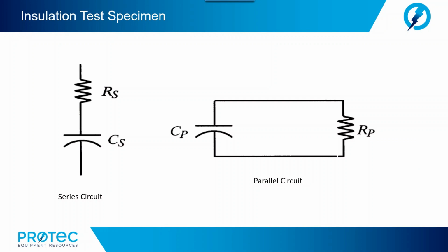Insulation systems associated with many types of high-voltage power apparatus and devices often consist of a mix of non-homogeneous component parts. As such, a complete and highly accurate schematic representation of an apparatus insulation system may be quite complex and difficult to compose, perhaps consisting of a number of resistor and capacitor elements arranged in many varied ways.